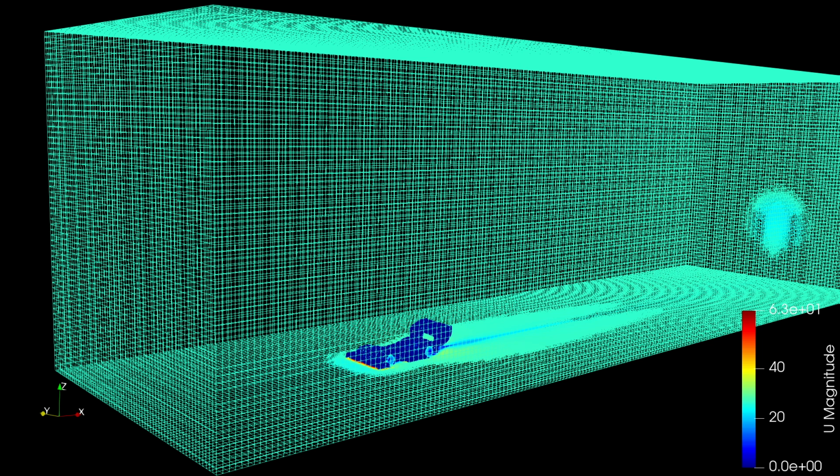So to design and evaluate the aerodynamics of the Hypercar, we're using something called computational fluid dynamics, or CFD. CFD works by dividing, or meshing, the area around the car into millions of tiny little cells. And computers can then apply a variety of different solver methods to calculate the airflow and pressure through the cells. Obviously, the more cells you have, the better the resolution of your CFD results, but the more computational time it requires. So basically you want to strike a balance between your accuracy needs for your particular application and the amount of processing time required to calculate all those cells.